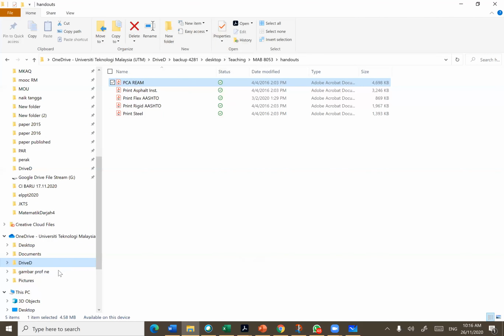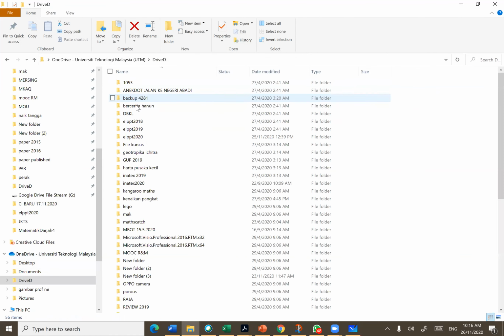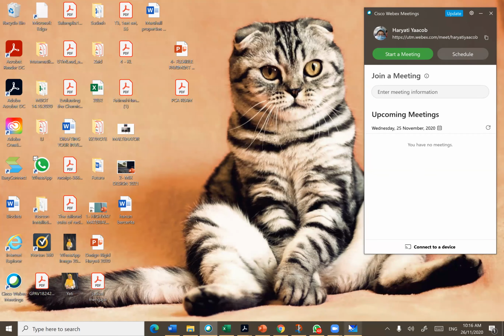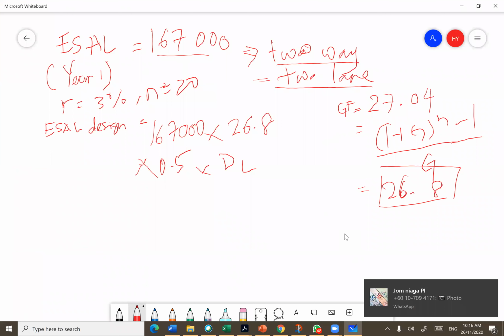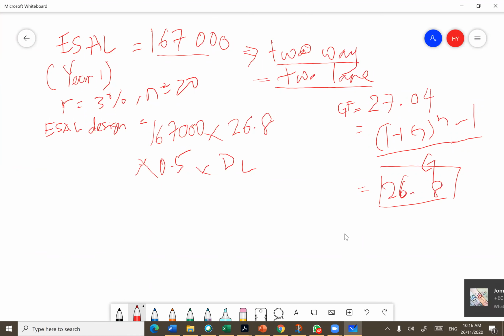Alright, I go back to my 80-100. The range, if you look on the table given, for 2 lanes per direction is between 80 to 100%. So we take the minimum one. Let's just take 80%. So for the lane distribution, we multiply with 0.8.